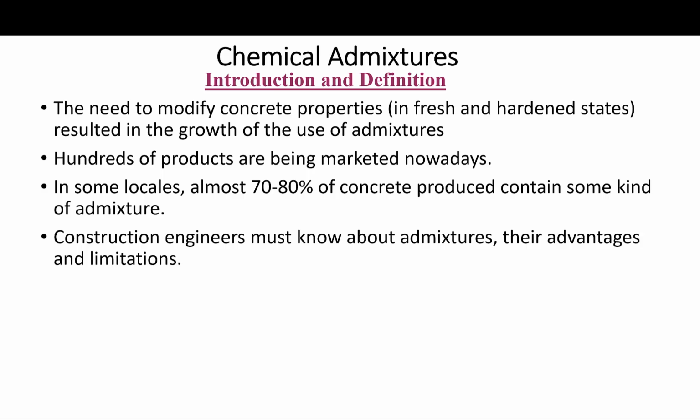Generally though, admixtures are used in concrete to improve workability, accelerate or retard setting time, control strength development, and enhance the durability to frost action, thermal cracking, mitigate the alkali aggregate expansion, the sulfate attack, and the corrosion of the reinforcement. Okay, the important classes of concrete admixtures, their physical and chemical characteristics, mechanism of action, applications, and side effects will be described in this module of the class.